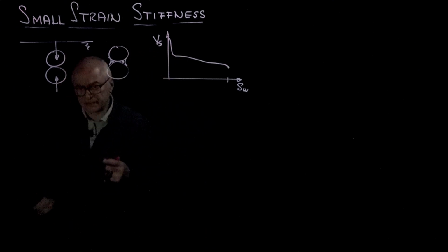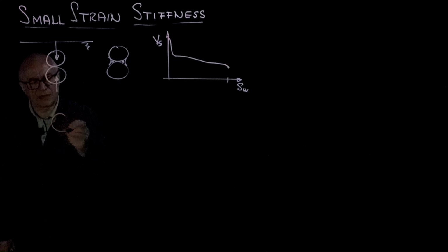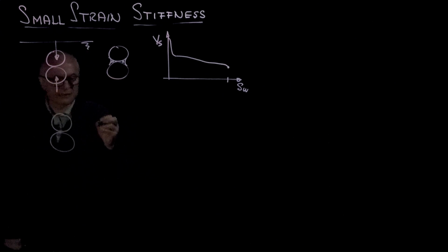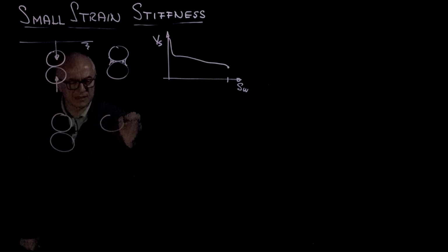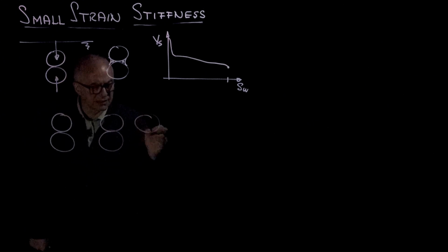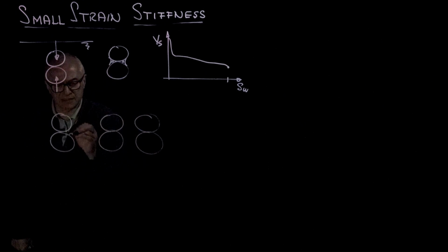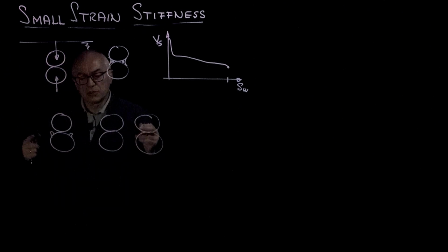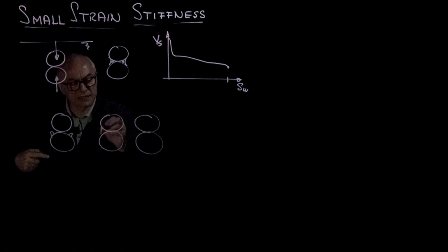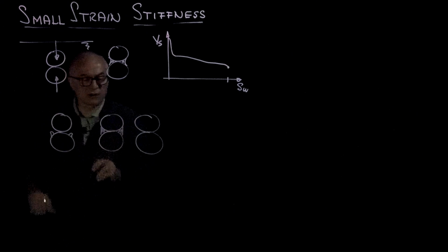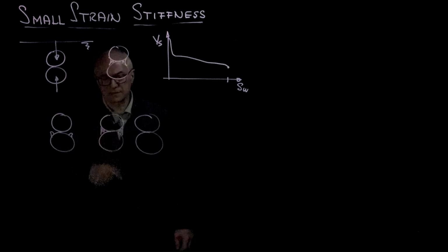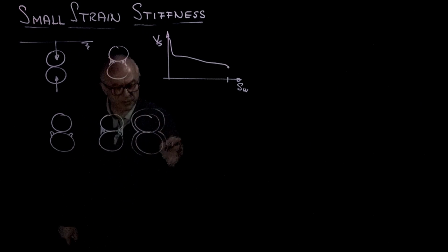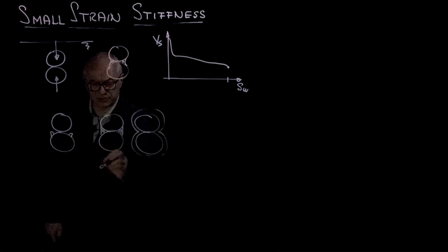The other one that is a very important effect is if we go back to cementation. We mentioned that one in the video on contact mechanics, and cementation could happen in different ways. Crystals may precipitate on the surface and have no effect, or it could be that crystals precipitate near the contacts, primarily during a drying process. This is the case of loess. Or it could be that crystals precipitate everywhere, probably because there was a biofilm. So this is during drying.